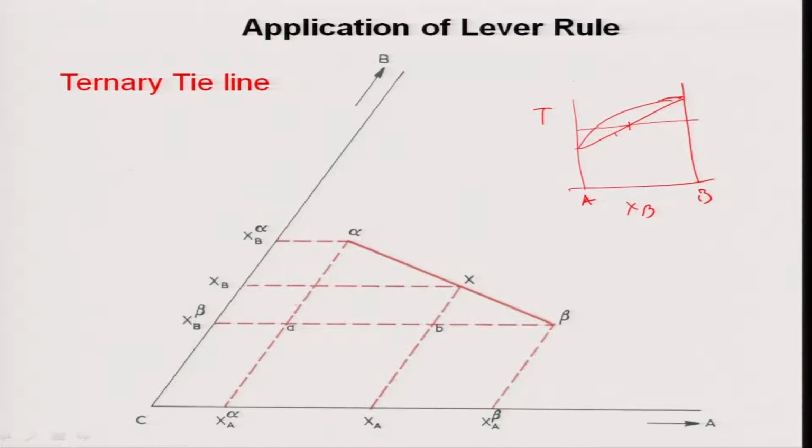This is the solidus, this is the liquidus. It connects that solidus with the liquidus. So, what does it tell you? It tells me the liquid composition and the solid composition. So, I can draw many tie lines and find out. Whenever you talk about solidification of an alloy, I just follow the tie lines to know the composition of the solid and liquid phase. The same thing can be extended in ternary.